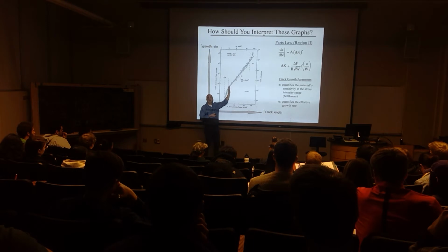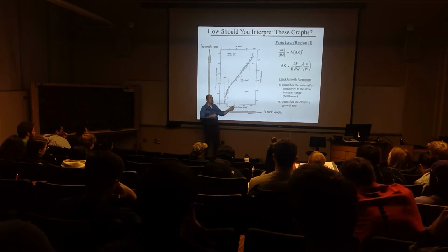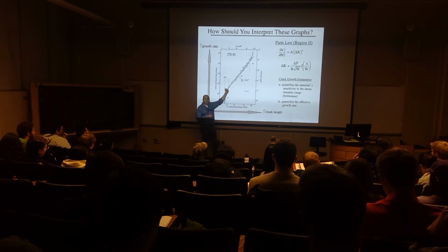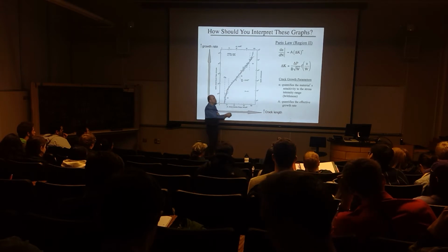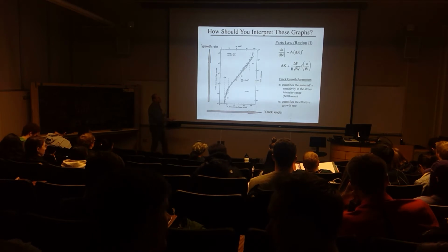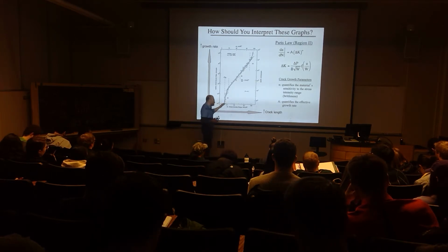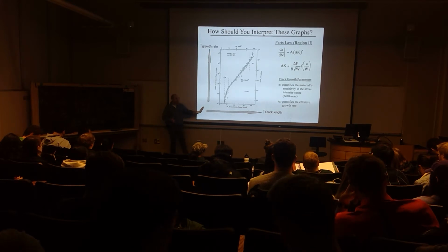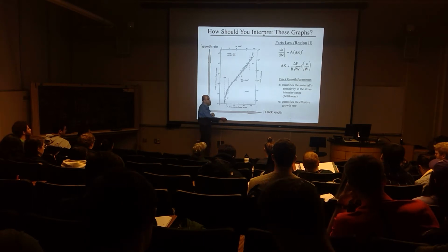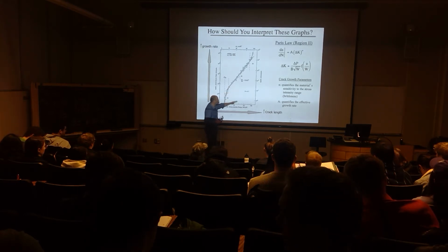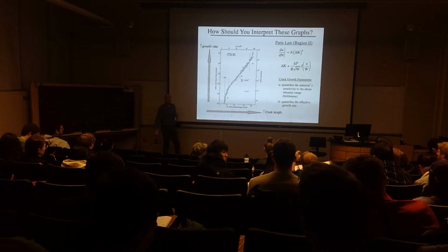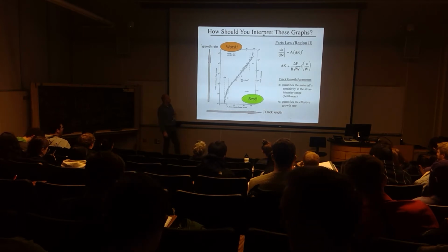Versus one that goes like this. If I have a material like this and the crack starts increasing a little bit in length and then just takes off like it's in a race, that's not a good material for resistance to cyclic crack growth. So n, that slope, quantifies the material sensitivity to the stress intensity range. And then C is just going to be an intercept where the stress intensity range is equal to 1, because in the log-log relationship, you can't see it, it's down here on the far left. It really represents the effective growth rate. So you can think of C as the height. The larger the C value, the more the distribution shifts to the right, or shifts upward.